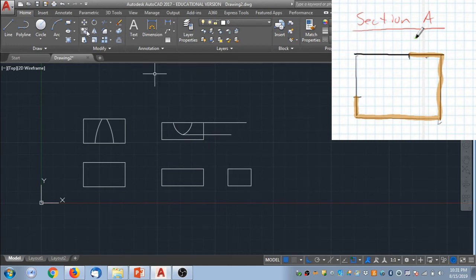And then I'm going to copy the box back up. I'm going to use the top line and align it with the top line there, so my section cut is aligned with the front of my box. Now, the thing that we're going to do here, we're going to extend that second construction line out to the box by, if you click down on the trim tool, there's an extend tool, where in the extend tool you pick a destination you want a line to end, and it will jump the line out to that point.